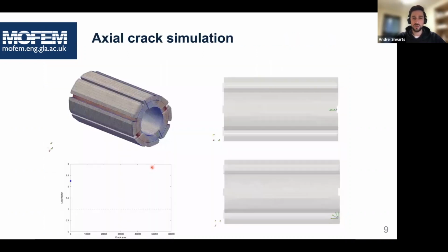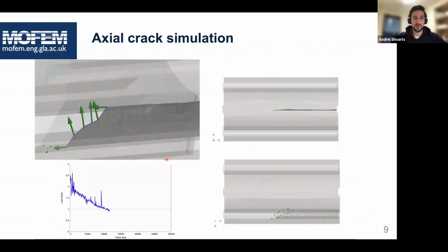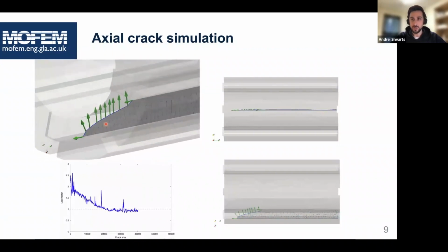And that's why for some years, there has been work going on around MoFEM on creating a framework for predicting propagation of those cracks, for simulating that, and also trying to analyze when those cracks will propagate in the lifetime of the reactor. So here you can see a finite element mesh where the cracking is taking place, mesh of the brick, and you can see how the crack is propagating along the axis of the brick.